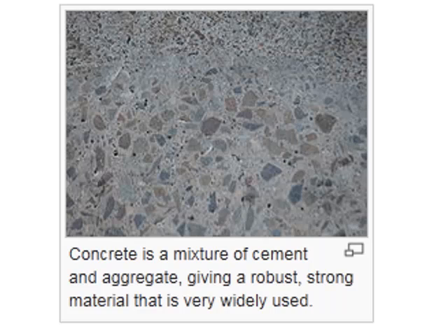They are physically separable. But if you compare the same thing with an alloy, say for example steel, it is made up of iron and carbon. But when you cut a steel rod, will you find the iron particles and carbon particles separately or physically visible to you? No. So that is the main difference between an alloy and a composite material.